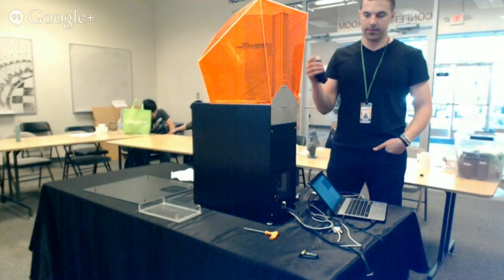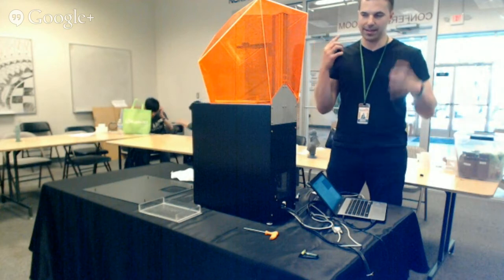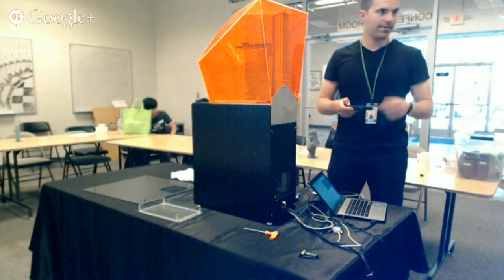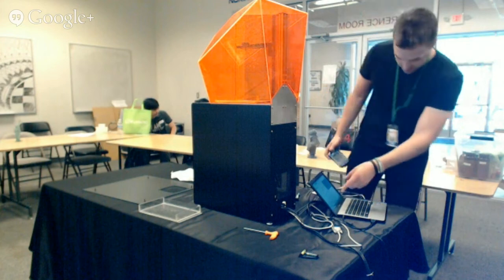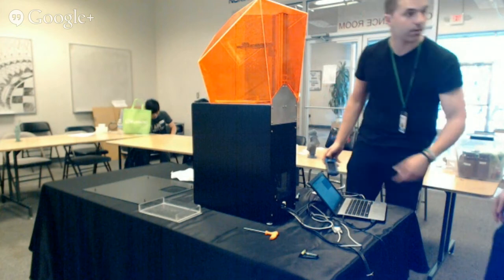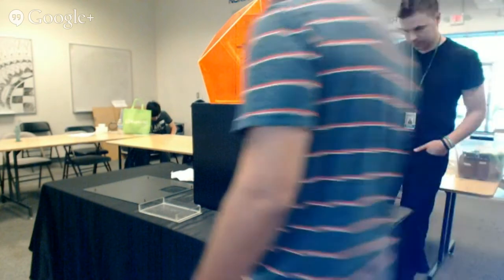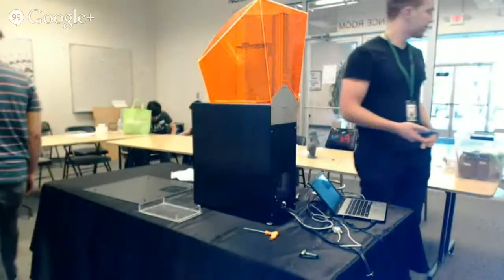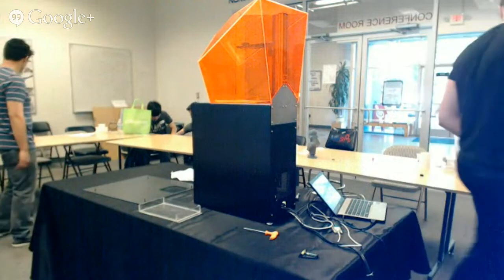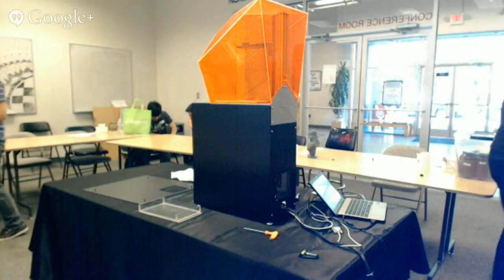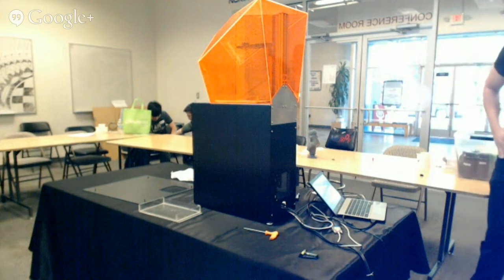Do you have anything on, essentially, how do you determine the exposure per exposure just through iteration? Because here you have 15 seconds. There's published ones. They're on Kudo3D's website, right? Ted has done a lot of experiments with different resins. So for the resins that they've used, he has information about, given the resolution, what the different layer exposure times should be. So he's got guidelines for all of those.